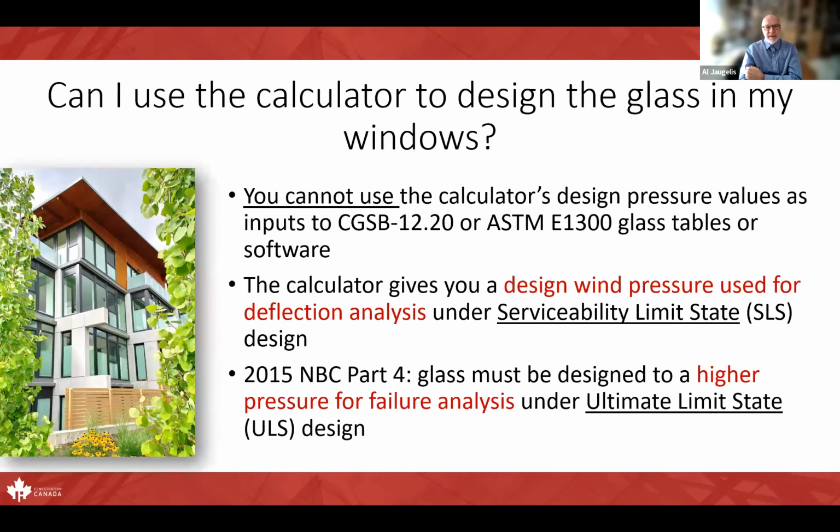Here's the question that our caller had. Can I use the calculator to design the glass in my windows? Dave, do you want to maybe touch on this? Yes, you can. Keeping in mind that if you're using ASTM E1300, you can't use the 0.75 factor, and when you're using 1220, you can. And so I use a calculator that's based on 1220 that is published by IGMA.